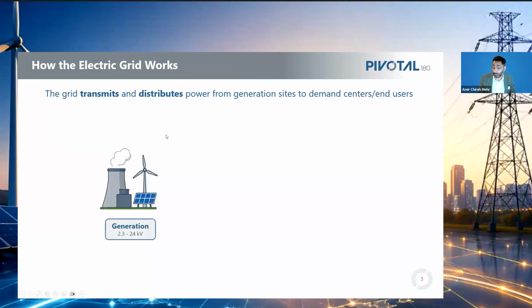You have power plants located where the resources are. A nuclear plant oftentimes is sited near water to cool the reactors if it's a water-based cooling system. Wind and solar obviously are sited to be near wind resources and good high quality sun, but also accessibility to the grid to transmit that power elsewhere. Natural gas or coal-fired power plants, ideally you have them close to the grid, but also close to the sources of the fuel that goes in.